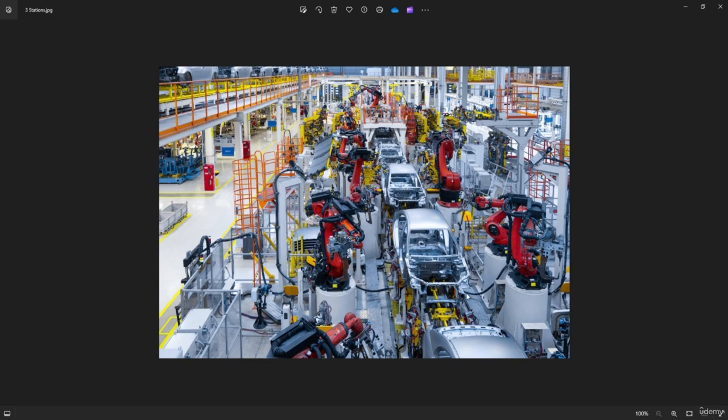So we are inside a functional assignment, which is a plant, and that will be the NF Click Robots plant. We are inside a building, which is the welding shop building. That's your functional designation. And now we are on the installation site, which is station 01. That's the station we'll be creating.